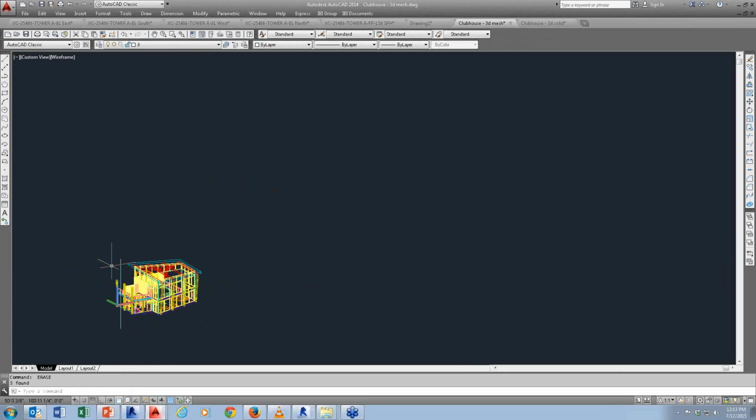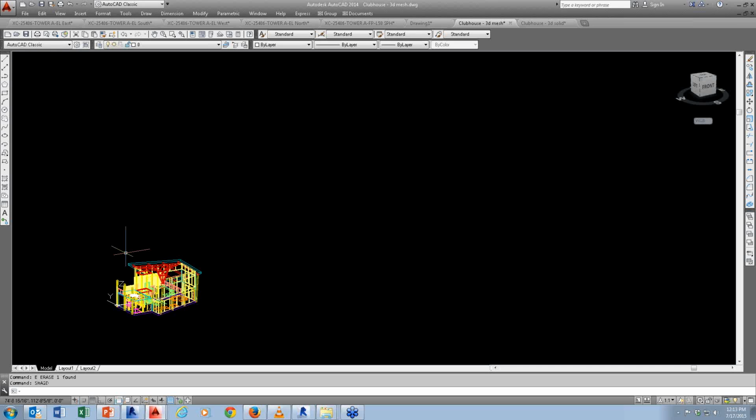what you want to do is that if you're planning to use AutoCAD to generate your 2D information, you have to understand that AutoCAD will not do everything, okay? So for 3D Solid, you can generate information, whereas 2D Mesh, you cannot generate information, but you can actually use it to generate like elevation. Section is a little bit hokey, but you can still do it. I'll show you how to generate a section from this.